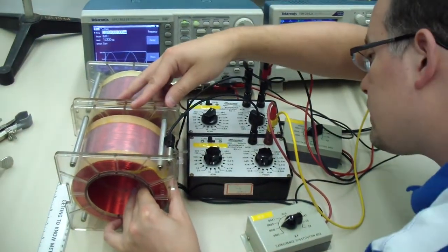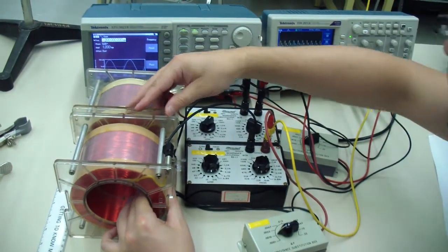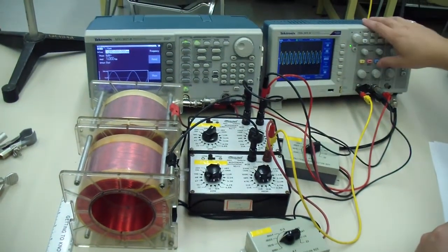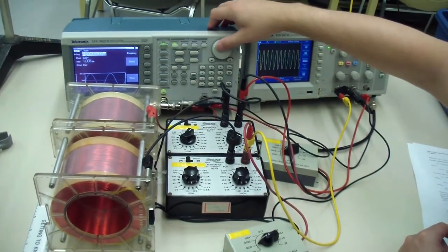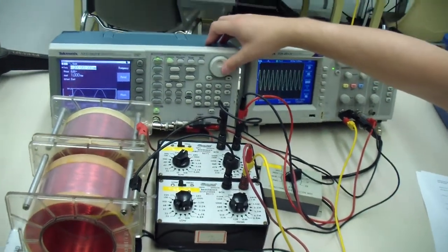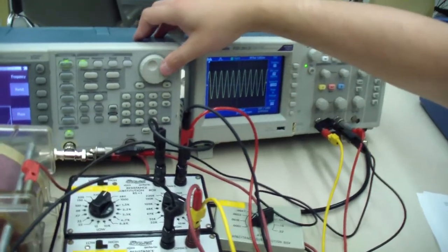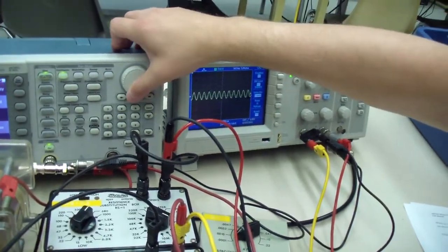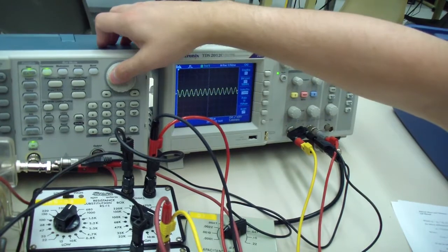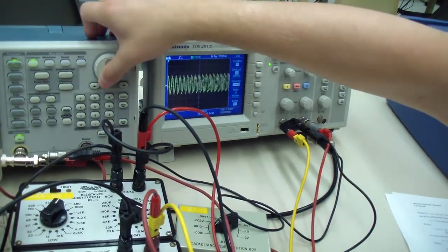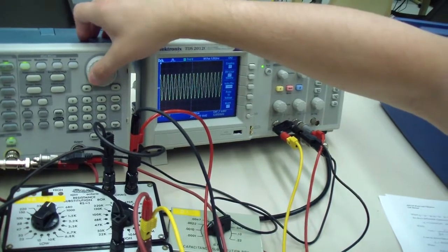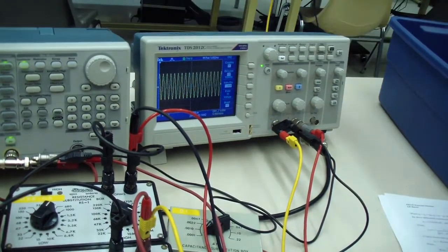Separate the two inductors, say by 1 centimeter. Set the oscilloscope to display only the coupled capacitor, which can conveniently be used to find all three relevant frequencies. Vary the frequency to find the two maxima and the local minimum between them. Record all three frequencies. Increase the inductor separation and repeat. Do this until you have a reasonable plot of each of these frequencies as a function of inductor separation.